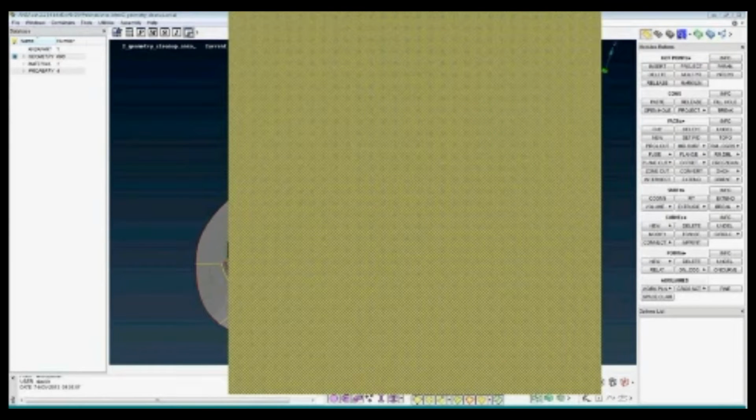In this geometry cleanup example, we will see automatic checks of the geometry, locating problems, project lines, connect, cut, create, delete spaces, automatic filling of holes, assign PIDs, fillet sharpening, and transform, and copy and move your model.